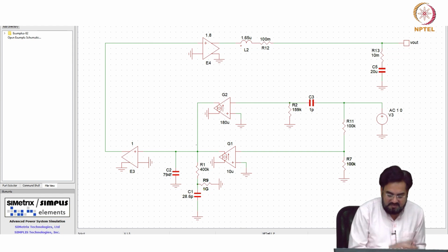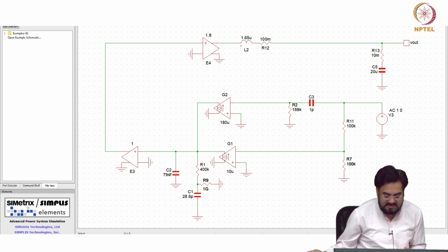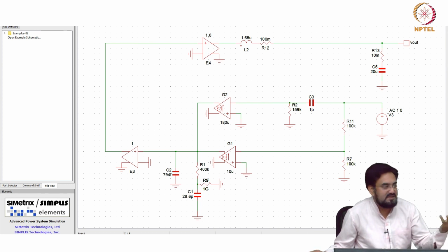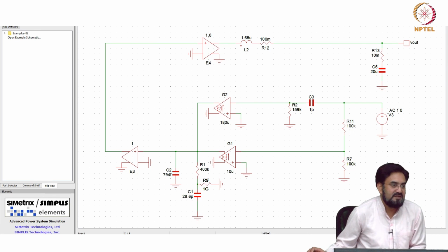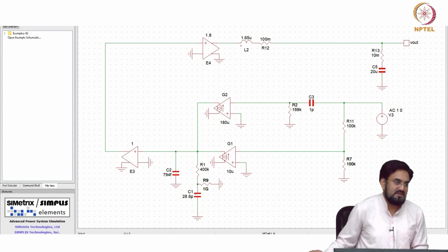Area, I don't know, you may get a similar area to what you get with the op amp, but here, if you look at the total cap, only 1 picofarad is required for the zero, while in the other case we are looking at 57 picofarad. So 2 caps of 57 picofarad, but here the total cap is less than 50 pico, almost half of that. So the total cap is actually 1/4.